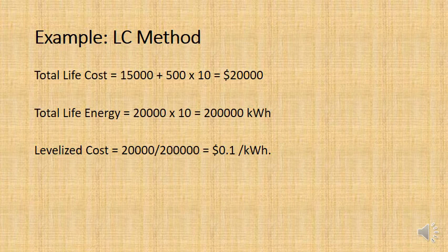So the question is, should we build the solar panels? Well, if we were going to just do a plain levelized cost method, we would take that 10 cents per kilowatt hour and compare it with the standard, what we currently use, gas electricity from the mains and also the diesel generator.